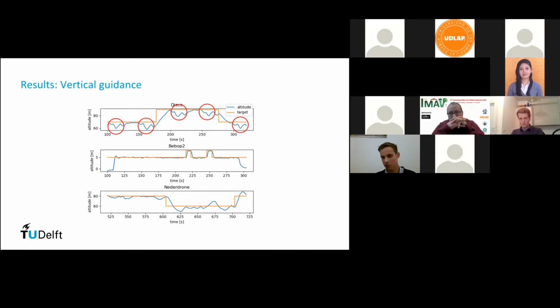This is because we don't have full yaw control in this drone, so we miss one axis of control, and as a result of this, it drops altitude in the turns. But if you look at the step, it is able to climb and descend according to its step inputs with an accuracy of about 10 meters.